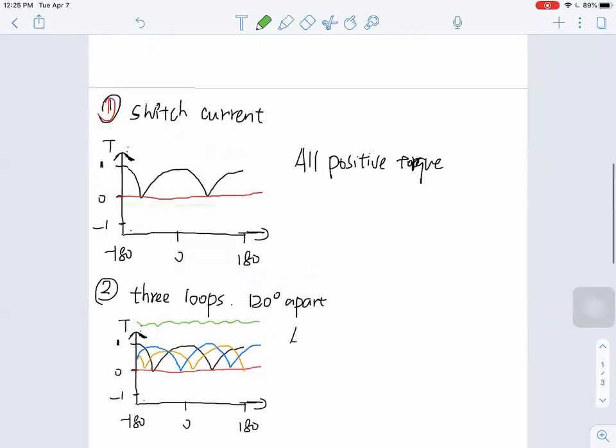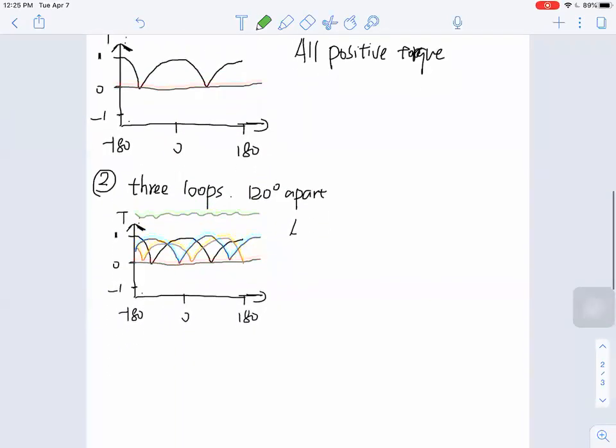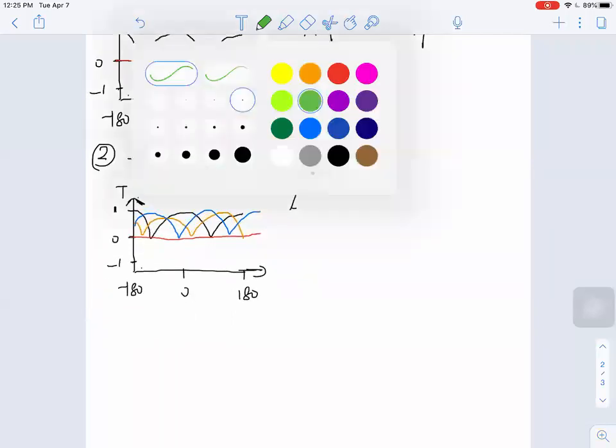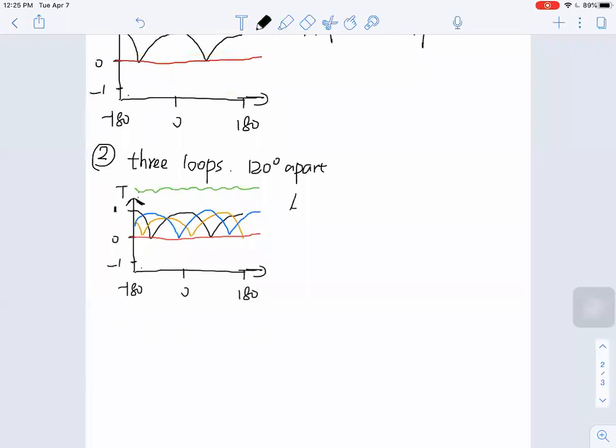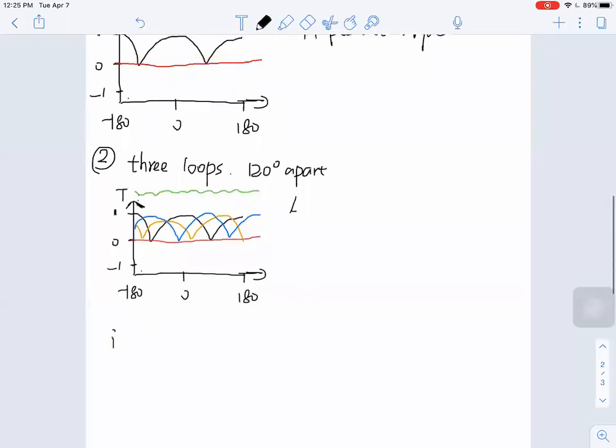So another thing here, we're talking about just adding more loops, and there are potential problems that the motor could still suffer from insufficient torque. And if we want to increase torque, we mentioned from the basic equation, we can add a stronger magnetic field, or increase the current, or increase the length of the wire.